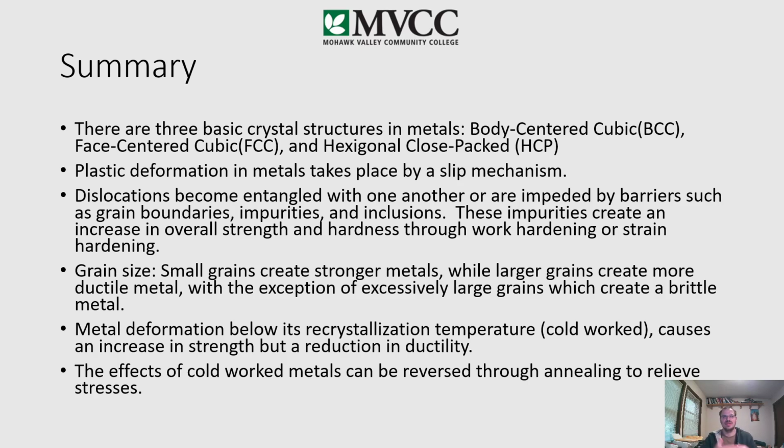And once it does, essentially that's where it starts catastrophic failure. So that's why they're able to hold more. They don't stretch as much, right? So they're less ductile. And this is all done through work hardening or strain hardening.